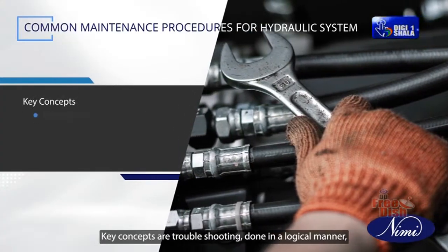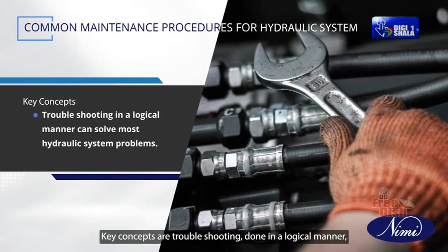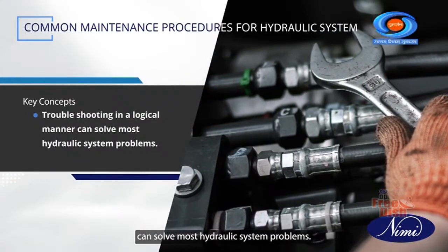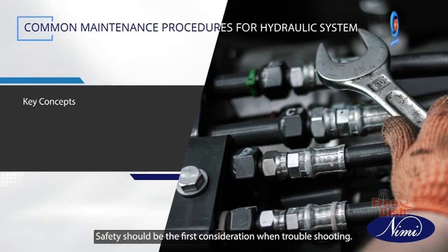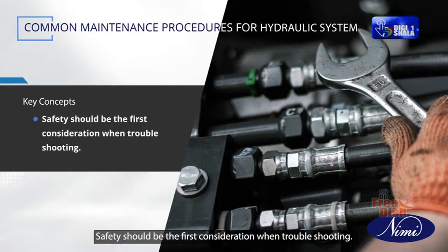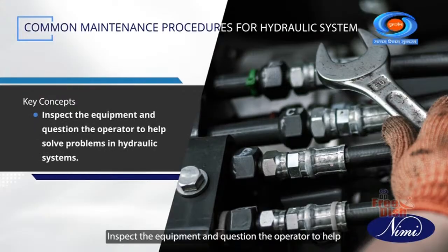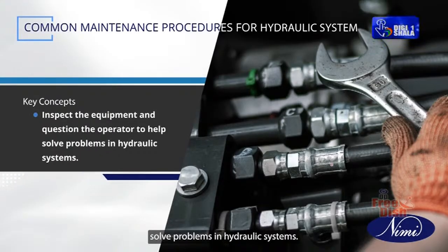Key concepts: troubleshooting, done in a logical manner, can solve most hydraulic system problems. Safety should be the first consideration when troubleshooting. Inspect the equipment and question the operator to help solve problems in hydraulic systems.